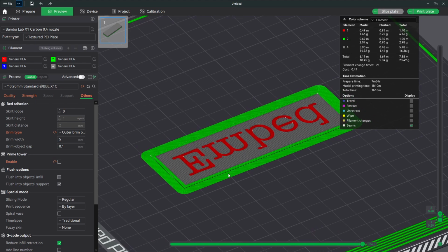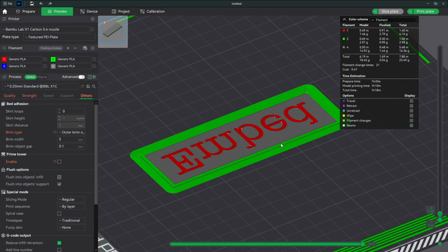They've made this a little bit smarter. It's looking at which one is on the perimeter now. The algorithm originally, and I believe still, looks at the volume of material going down to try and decide which one to print. There was a blurb somewhere saying that they've made it a little bit smarter about looking for perimeter colors. But let's say you are unlucky and you have a model where it decides it wants to print the gray first. And in doing so, you're going to have a green border with a gray brim stuck to it that is going to discolor the edge of your print. You don't want that.